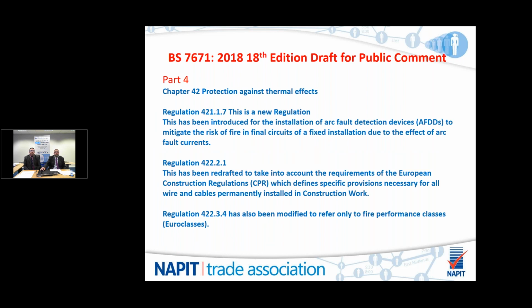Within Chapter 42, Protection Against Thermal Effects, there's a new regulation being introduced, 421.1.7, and it requires the use of arc fault detection devices, which will mitigate fire risks where faults occur due to arc fault currents within the circuits. This is a requirement to be installed if there's a risk of those faults occurring within certain installations. It's not a requirement to install them in every installation. They have to be looked at and assessed, then installed if required.